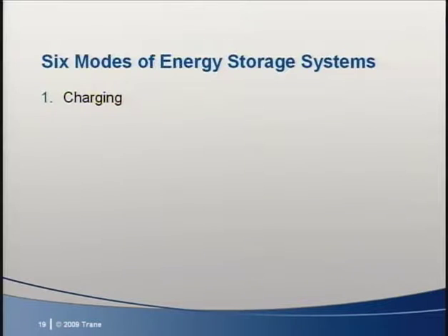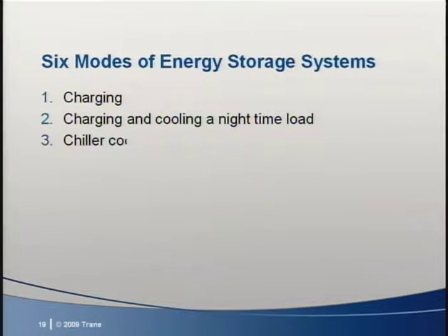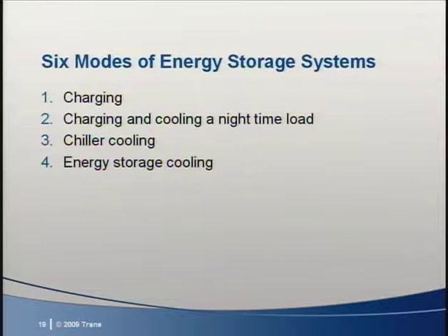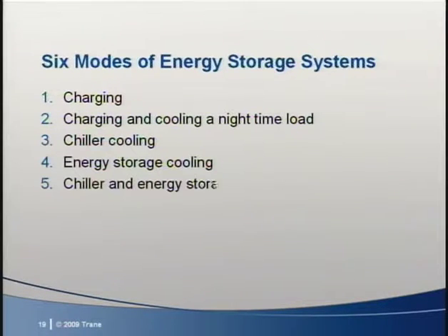These 6 modes may not be used on each and every project, but having the ability to change modes is an important aspect of flexible energy storage design. The 6 modes are charging with a nighttime load, cooling with chiller only, cooling with ice only, cooling with chiller and ice, and don't forget off. Understanding these requirements helps one understand how ice on pipe internal melt came to be the market leader for comfort cooling projects. So keep these modes of operation in mind as we proceed.